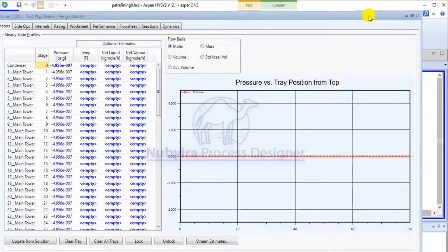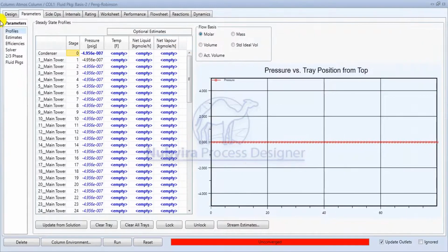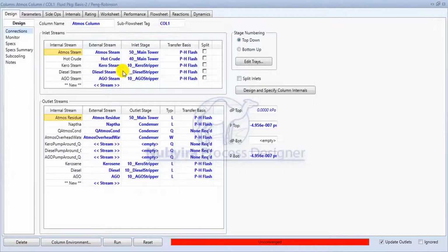Okay, although I've already defined the input, I'm not using it. I'm just writing the topology of this distillation based on this table here. So it is a reflux absorber column. That is, we have only a condenser, we don't have a reboiler in the column. That's why the bottom is empty here. For the condenser, the distillate is in liquid form, so it's a total condenser.